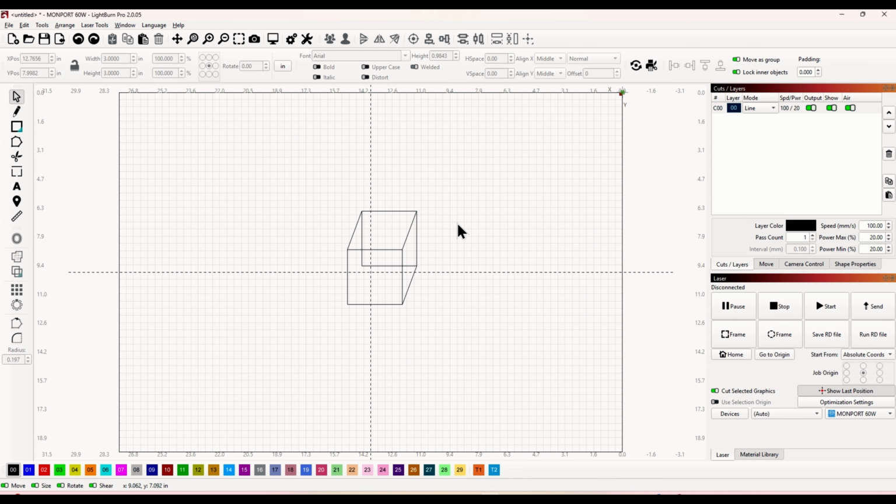So what are we actually looking at? If you will take your block and look at it in the same orientation, what you will find is you will only see this face up here or this plane. You'll see this plane and this plane, which means these lines here and this back here right now are hidden, or as we were talking about earlier, they would be dashed. This line would also be dashed, which I didn't draw for purposes of clarity.